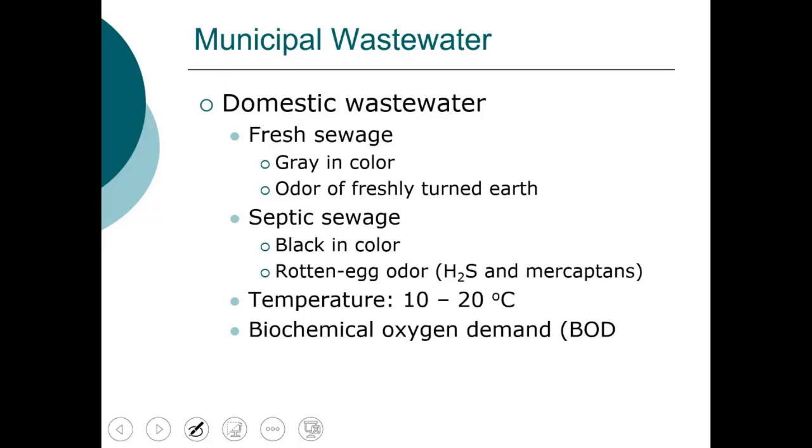So it's a significant distance from that point to the East Lansing treatment plant. Not surprising, that results in the absence of oxygen and sewage going septic. So for the East Lansing plant, one of the challenges that they have to deal with is this very long residence time in the sewer system.